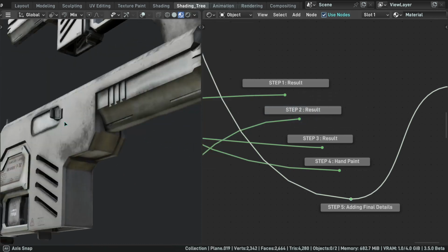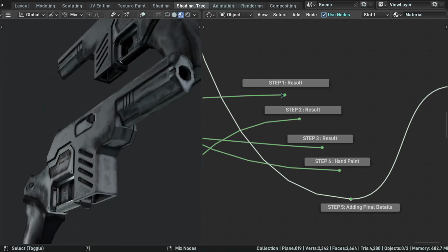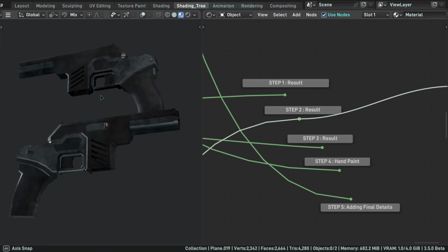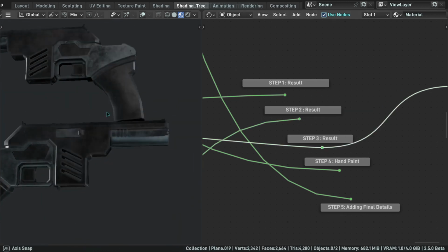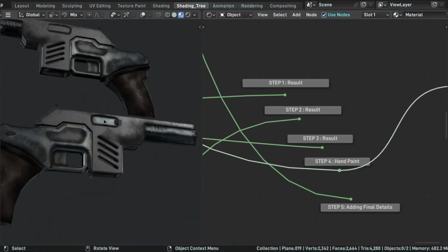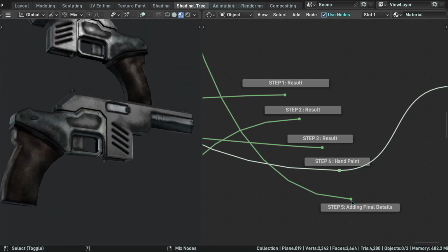And we can change here the HDR environment to see how this shader will behave in another type of light and reflections. And you can see that depending on your environment, the same material can look drastically different. You should always test your materials in different light situations to see if they behave properly. And here are the 5 steps on a different HDR environment and the final result.